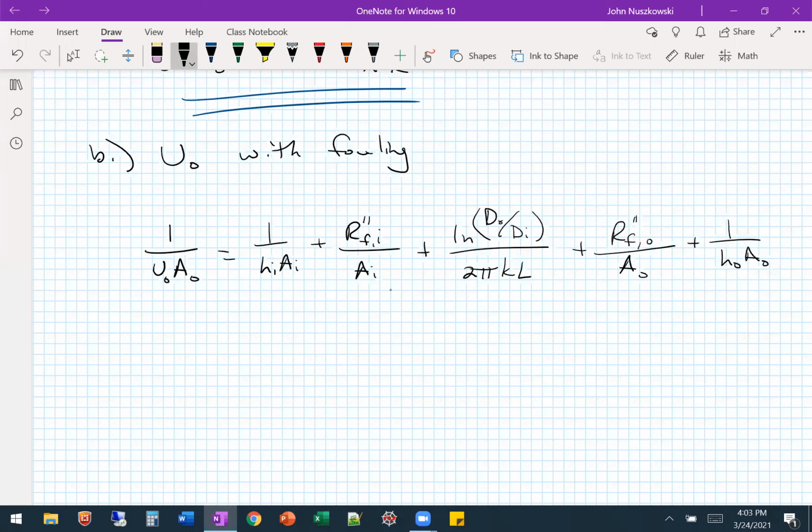All right. So back to our equation from our thermal circuit, which is 11.5, again for an unfinned tubular heat exchanger. We have that extra resistance back on the thermal circuit, right? So we just have no fouling on the outside surface.